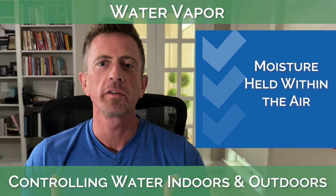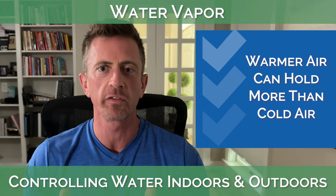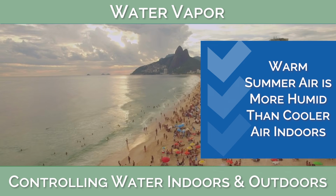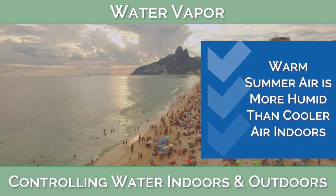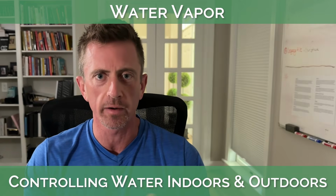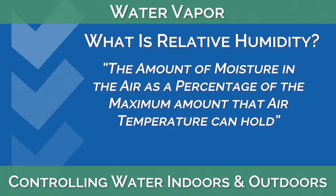Water vapor is moisture held within the air, and as a rule, warmer air can hold more water vapor than cold air can. This is why in the summertime, the warm outdoor air is more humid than the cooler air inside your house. And in the wintertime, the warm indoor air is more humid than the colder outdoor air. Relative humidity is basically the amount of humidity or moisture inside the air as a percentage of the maximum amount that air temperature can hold.